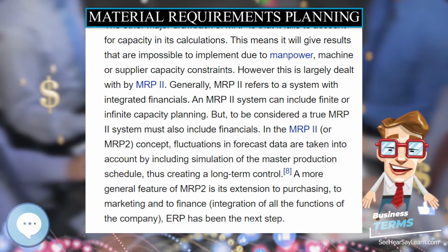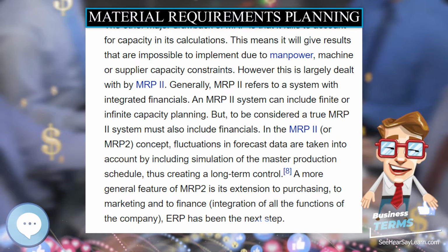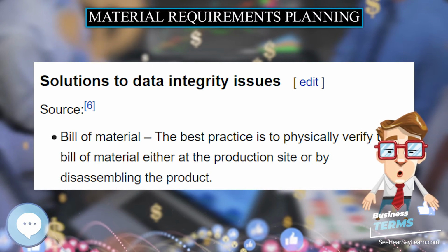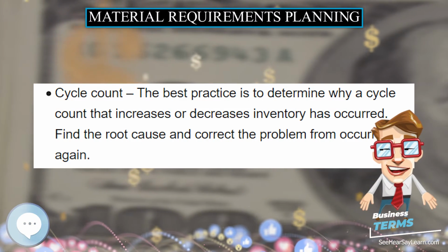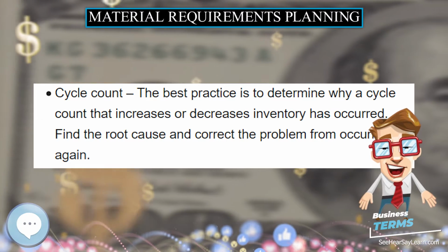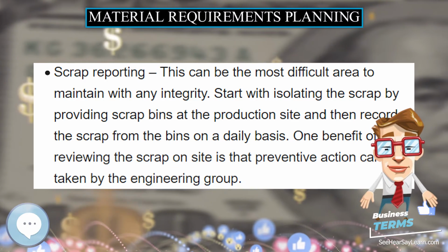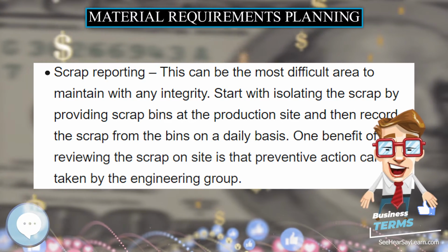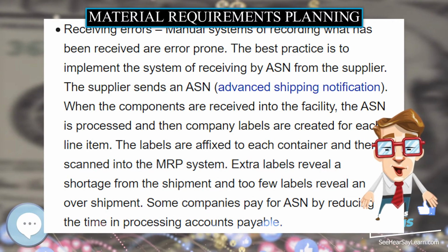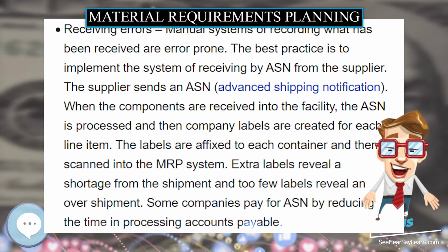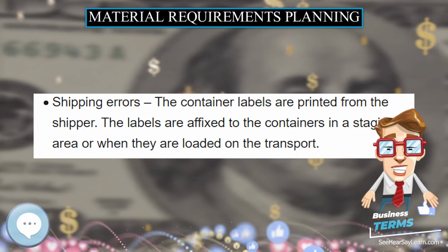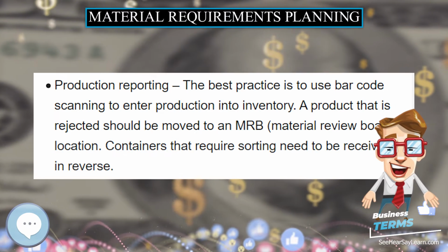The scope of MRP in manufacturing. Dependent demand versus independent demand. Independent demand is demand originating outside the plant or production system, while dependent demand is demand for components. The Bill of Materials, BOM, specifies the relationship between the end product, independent demand, and the components, dependent demand. MRP takes as input the information contained in the BOM.